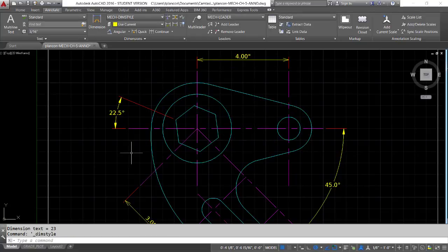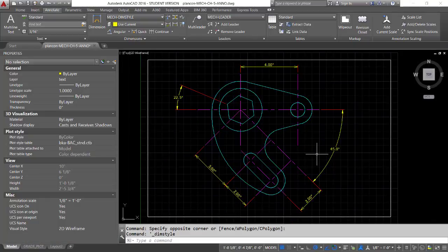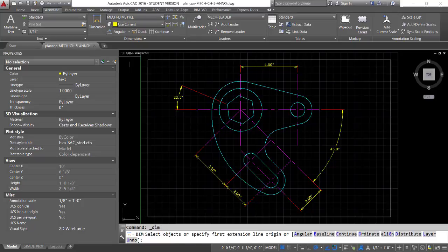So this is another example where AutoCAD will always draw the object correctly to the correct size if you tell it to draw it to the correct size. But it will show based on the settings you have for the kind of display you have for your units, for the precision. So the drawing is always accurate. It's really your display that changes.